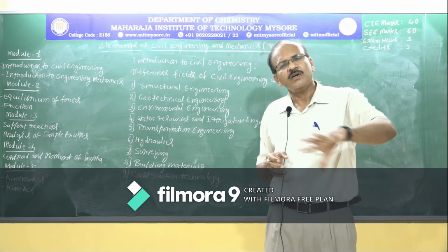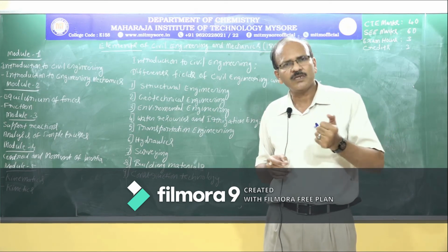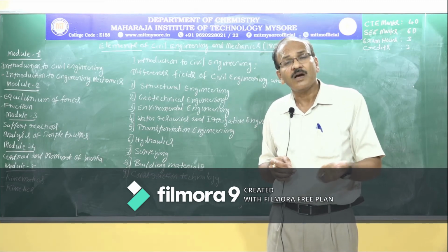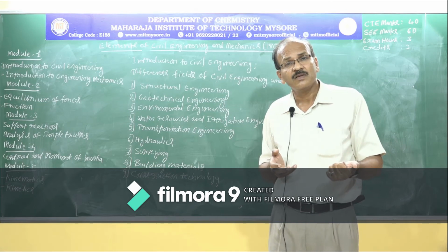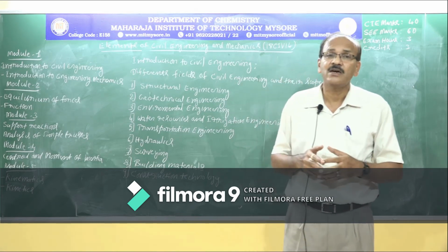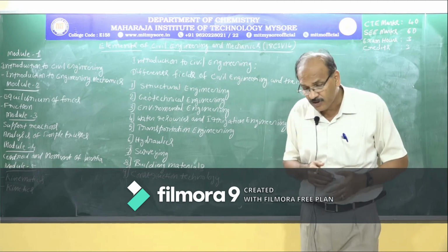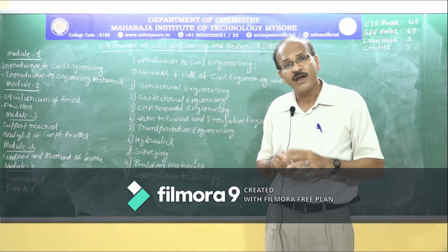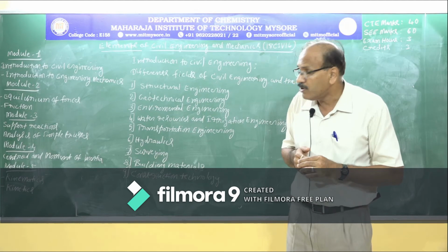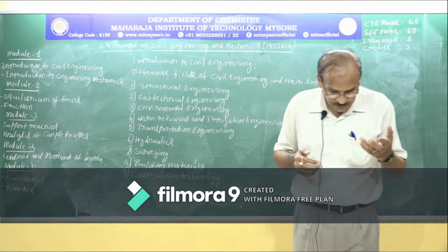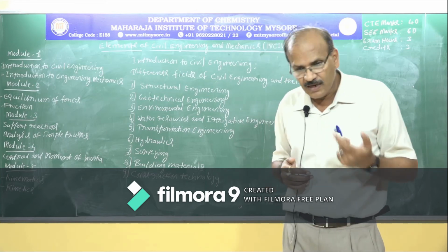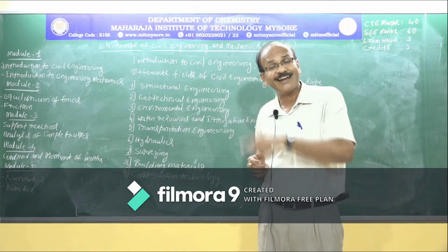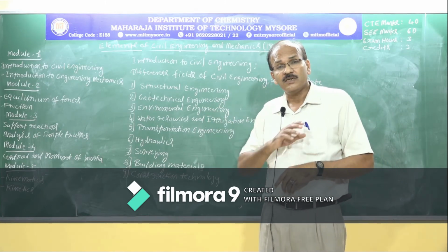Again, plane surveying, we are going to make use of different instruments to do surveying, like chain, tape, theodolite, dumpy level, compass to measure angles, theodolites to measure again angles, and also to calculate the altitudes and distance between two inaccessible points. And when it comes to geodetic surveying, where we consider the curvature of the earth, we are going to go for advanced surveying. Even now we are going to do survey using satellites, aeroplanes, etc.